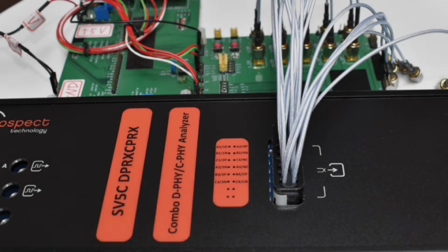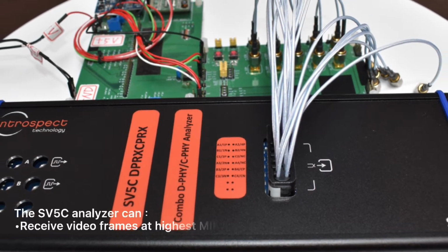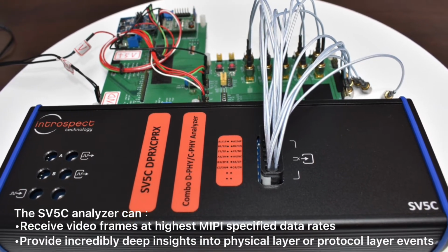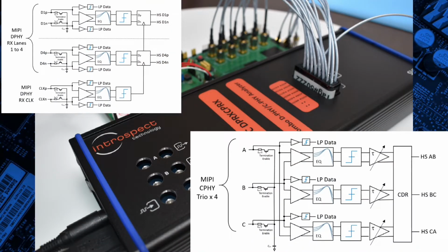Featuring a completely new analog front end and an updated software environment, the SV5C analyzer can receive video frames at the highest MIPI specified data rates, and can provide incredibly deep insights into physical layer or protocol layer events. Moreover, it has true combo input pins with the same set of pins either acting as a 4-lane D-PHY port or a 4-trio C-PHY port. LP/HS switching is handled automatically. There's no need for a termination board or other external equipment.